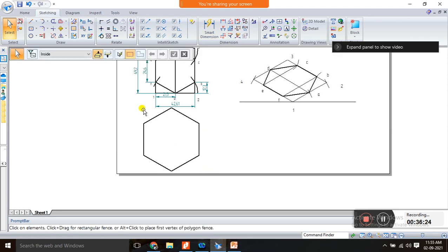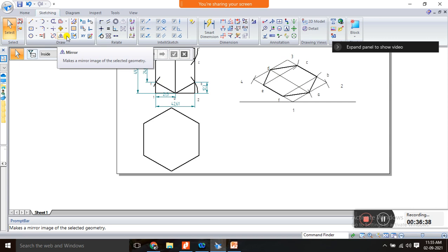And so this is a normal hexagon, okay. So you construct as it is with a normal dimension, okay, like this. Then with the help of scale you can reduce to isometric. That is another method, okay. First draw as it is normal dimension, then convert, or first convert and construct, then draw. So whichever one is convenient you can go with that.